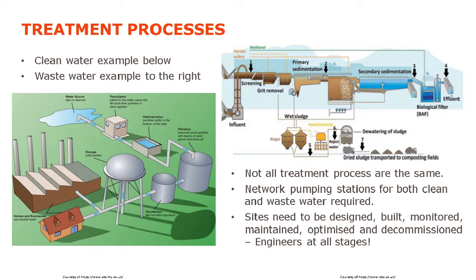Our sites are a working asset, a very real asset that you see up and down the country and all around the world. These assets have to be maintained, they have to be optimised. The effluent, the discharge could change, we could have more houses built. So they always need to be modified. You may need to put extra assets inside that existing site to try and make the effluent suitable for the discharge, to deliver more clean water to homes.